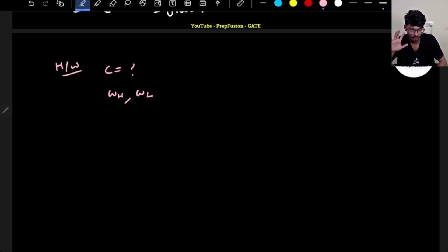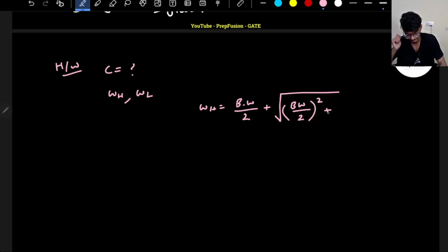I hope you remember the formula. What was the formula for omega H? Omega H was bandwidth by 2, plus, because it is the higher 3 dB frequency, plus under root bandwidth by 2 whole square plus omega naught whole square.